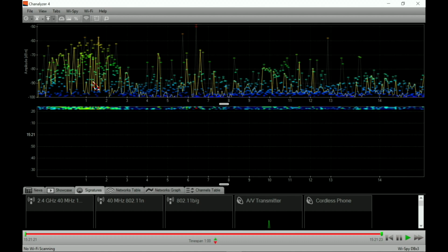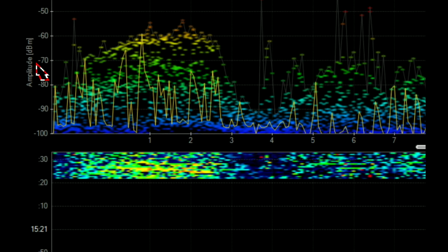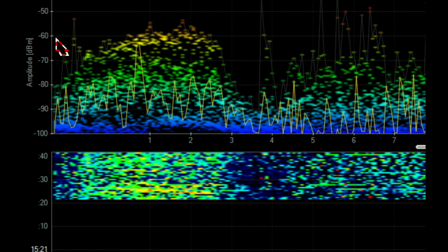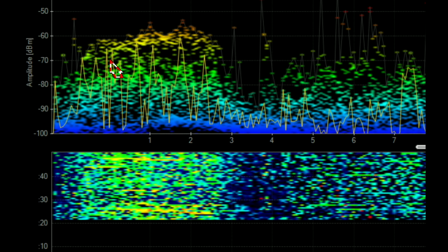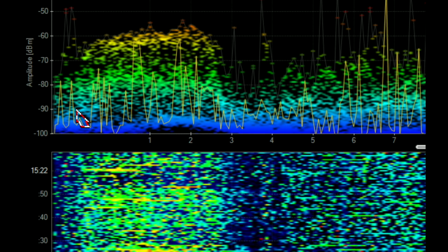Okay. So what you see here on top is the signal strength. Signal strength is measured in dBm, decibel milliwatt. So we are going to talk about this later. A good signal, a strong signal is around -60. And it's becoming weaker with a higher value. Below down, what we see here on the ground, that's what we call noise. That is activity which you always have from any kind of devices in the air. So the noise, if it's a good value, it's below -90, -95, or can even go lower depending where you are. In an industrial environment, it's probably higher from all the electric components and devices you have available.